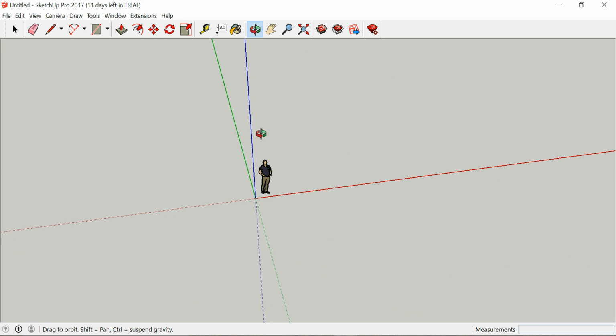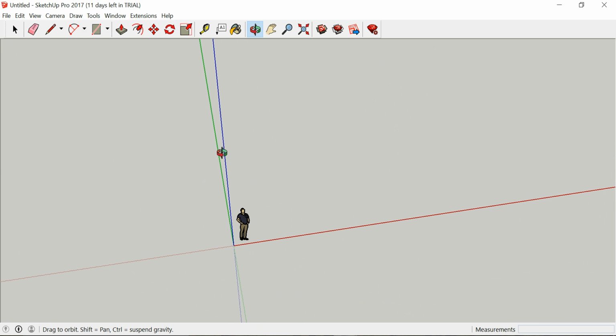If I zoom back out a little bit to give myself some distance, I'm then just going to draw how big I want the scene to be, so I can go off that point. I know the building needs to be 14,250, so it's 14.25 meters. And so down here where it says length, if I draw it out first of all, you can see down here it's going to change. If I just then type in 14,250, it will snap to that length, so we know that's where we want the width of the building to be.